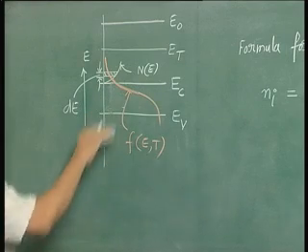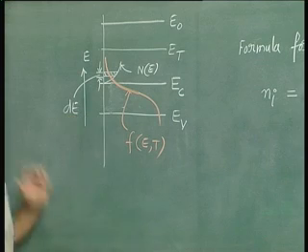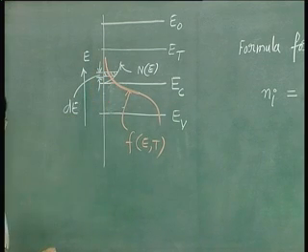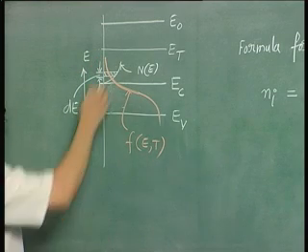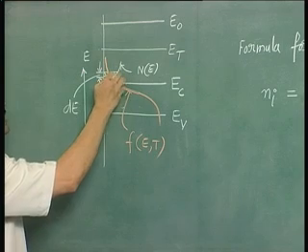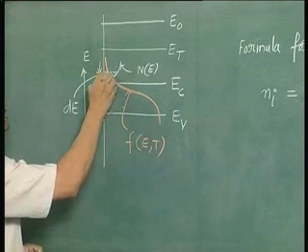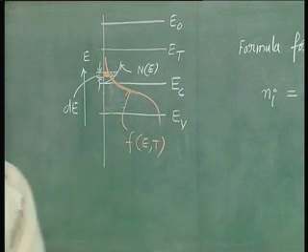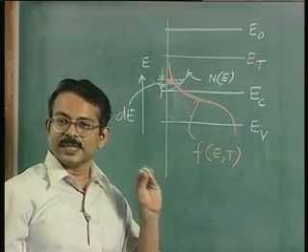So here all the three aspects have been shown in this diagram: the allowed energy levels, the distribution of available states over energy, and the fraction of states. So you multiply, so this is the available states, multiply this by this fraction, which means what is shown in this red portion, that is the number of electrons in the energy interval dE.